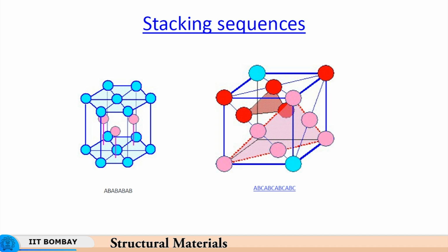These are events taking place at relatively high values of strain. We will see them a little later when we look at the mechanical properties, but just remember that these stacking sequences get disturbed, and this will affect the method in which the material will tend to soften beyond a certain limit of hardening.